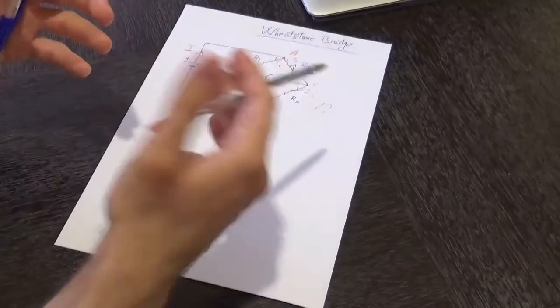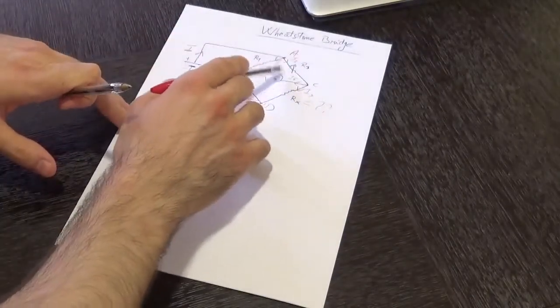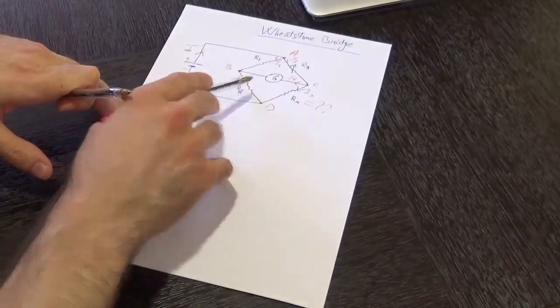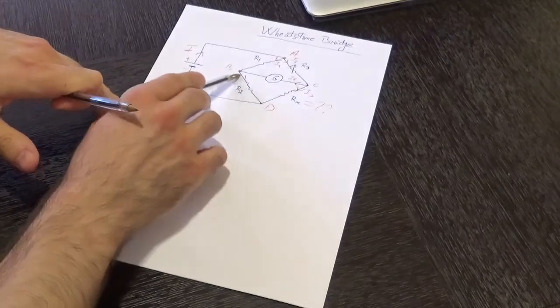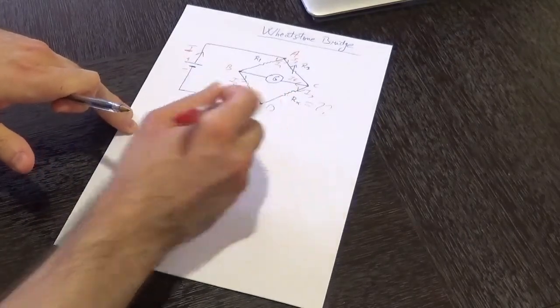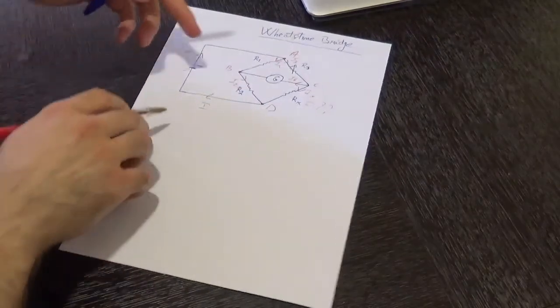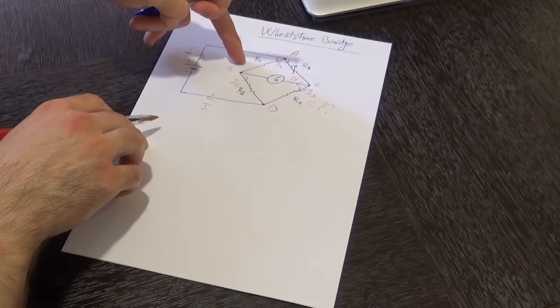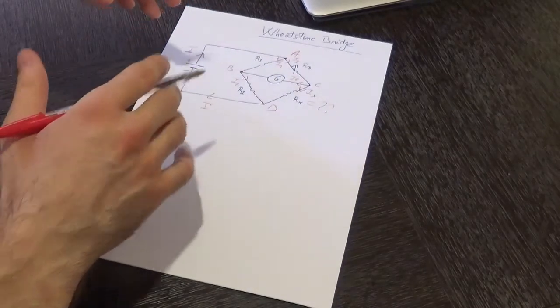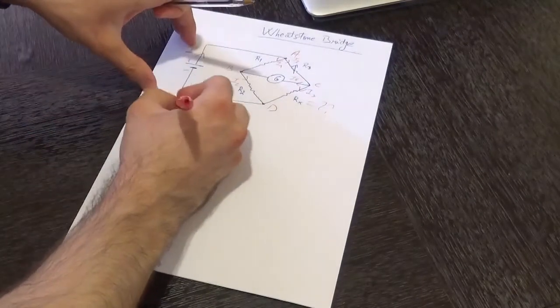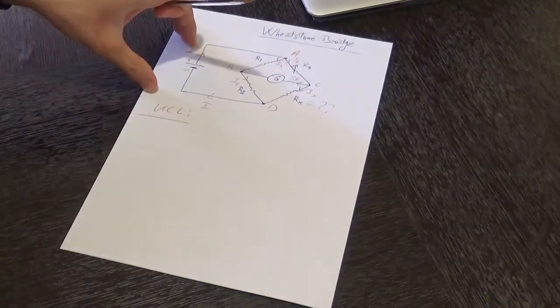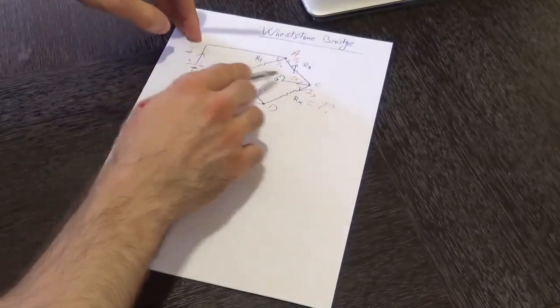choose the opposite one. So IG and I1 coming into B and giving out I2, and finally we have IX and I2 coming into node D and giving out the main current I. So now, after assigning the direction of the currents, we need to apply KCL, or Kirchhoff's current law. We are going to apply Kirchhoff's current law at node B and at node C.